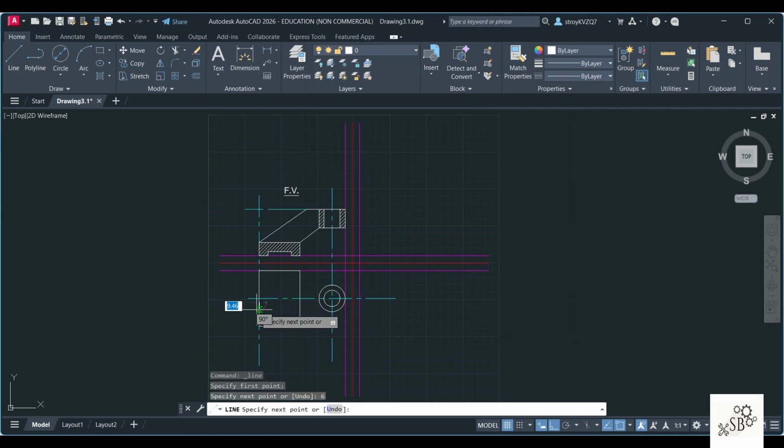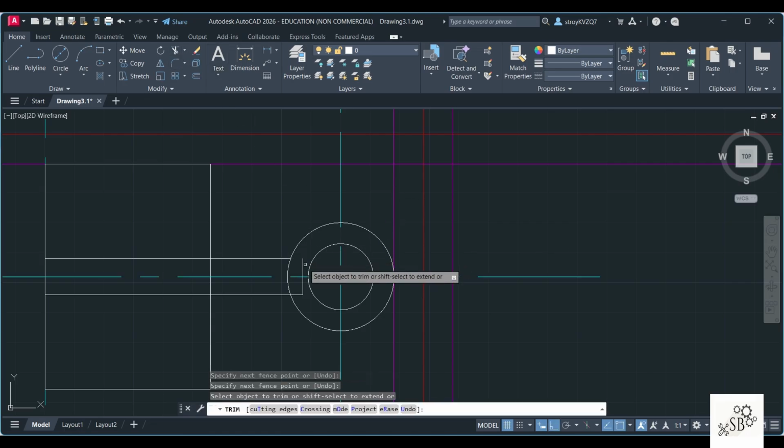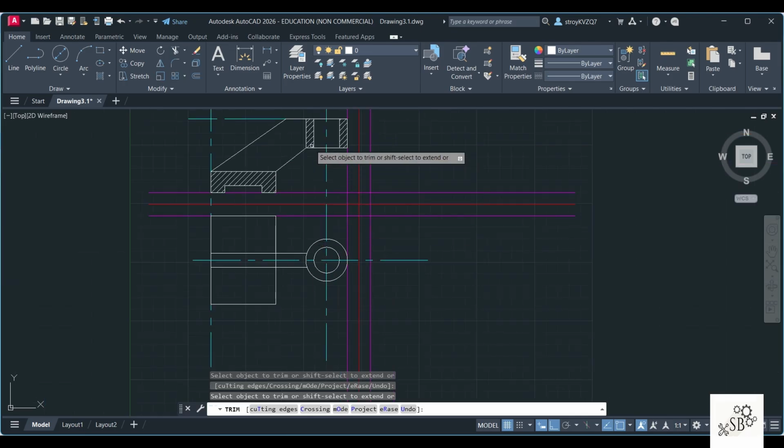This is 6. This will go right inside the circle somewhere. This is 12. And then I will end it here. This is an extra line. You just delete it. I'll use the trim option and I'll remove these extra lines. These are not required because it is actually going under this edge. So you're not able to see it.